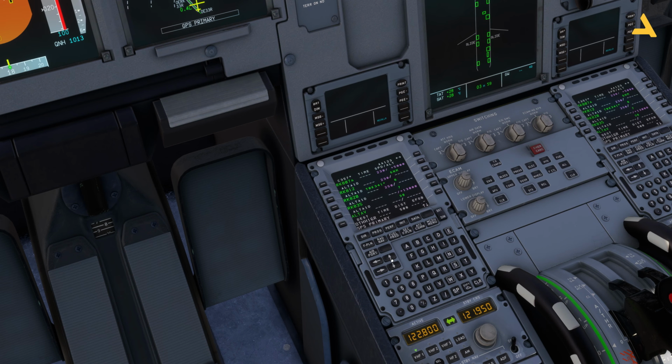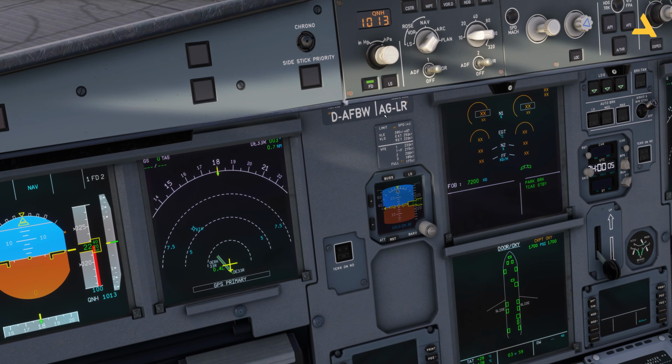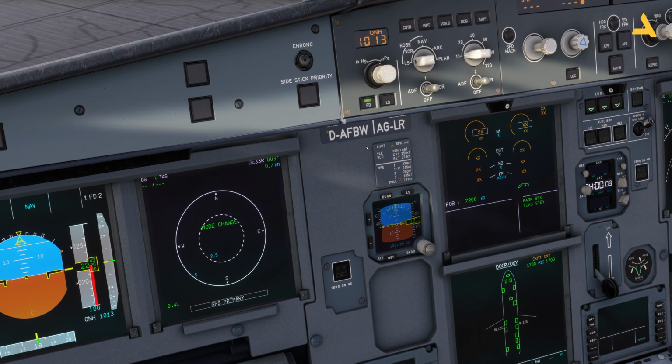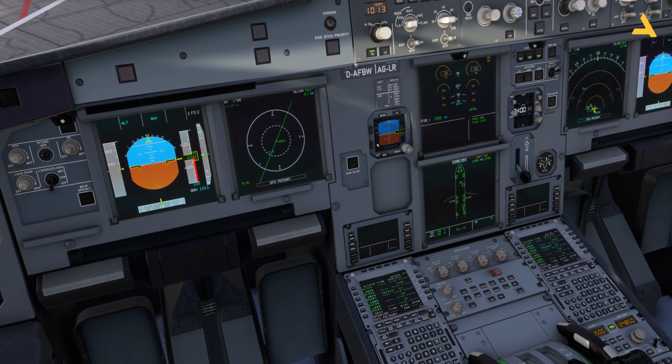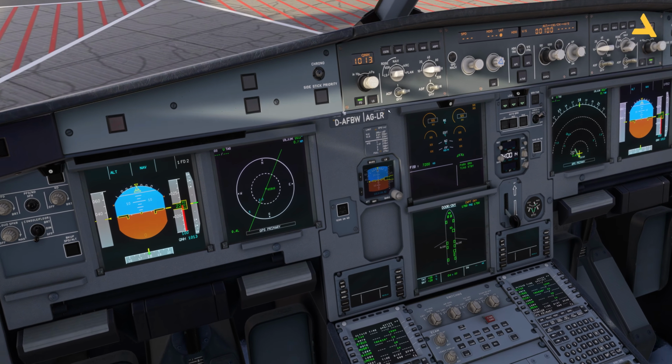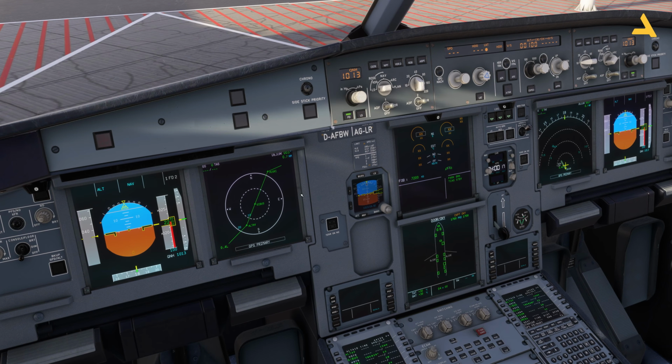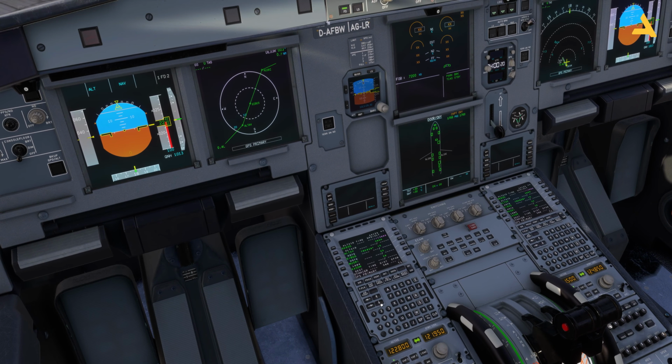Now if you go through the flight plan, you will see everything is there, and all the missing waypoints are now there. Just want to show you something. There will be a discontinuity in this flight plan, and it's over here. This is the only reason I select Qatar, especially for my videos, because this flight plan always has a discontinuity. If I go to this option, plan, you can go through the flight plan. Let me change this view. You can zoom in and zoom out by using this knob. And now you can see the flight plan is there.